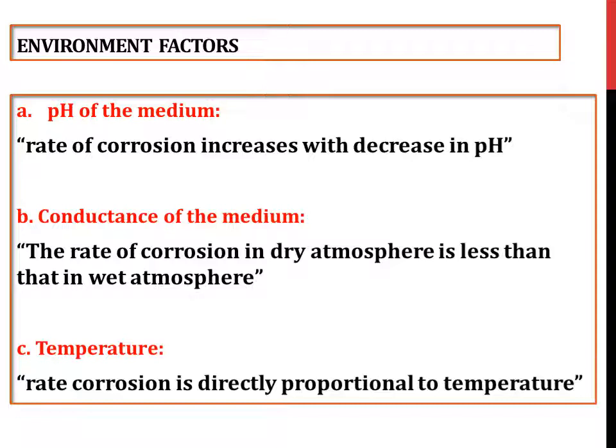In the marine atmosphere also, sodium or other chlorides near the coastal region always enhance the rate of corrosion. Under wet conditions or in the presence of moisture, the migration of ions will be faster and the rate of corrosion will be higher.